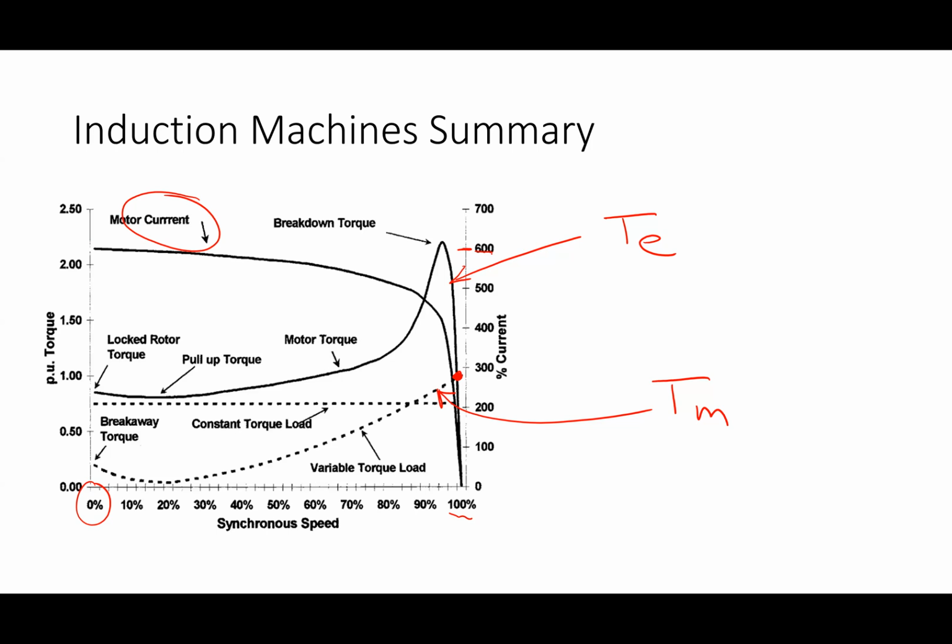That's about right. There's no hard and fast number on that, but most motors that I've ever seen are usually on the order of 6 to 8 times higher at starting. So if you go into the world of protection at SEL, one of those kinds of companies, with motor protection, one of the things you typically worry about is if the motor stalls, in other words, if it can't turn the pump or the compressor or whatever it's supposed to turn, you have to trip breakers, because basically you're going to be stuck at what we call locked rotor current at starting. All right.